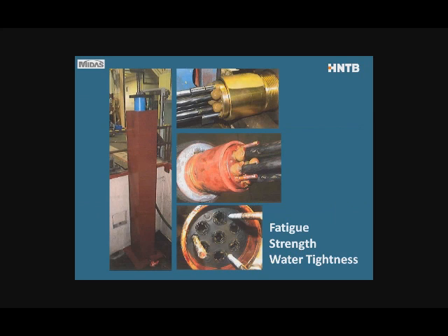Now these systems can be stressed as a whole, but the advantage is that the cable can be stressed one strand at a time. So that's the difference to the bridge strand, is the one strand at a time stressing. The Post-Tension Institute has published pretty extensive guidelines for design and testing of these stay cable systems, and Blennerhassett Island was subject to the same type of testing. So what they do is that the cable gets tested 2 million load cycles to a fairly high stress range,